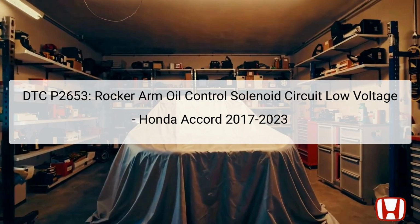The Diagnostic Trouble Code P2653 indicates a low voltage condition in the rocker arm oil control solenoid circuit. The rocker arm oil control solenoid is a crucial component in regulating oil flow within the engine. Specifically, it controls the variable valve timing, or VVT, which optimizes engine performance and efficiency.